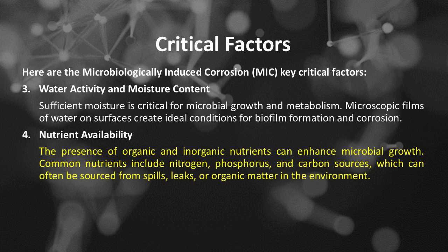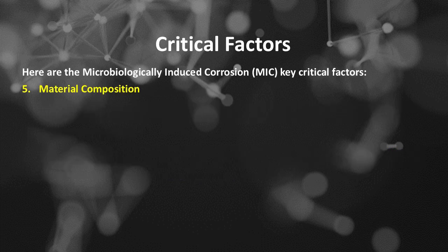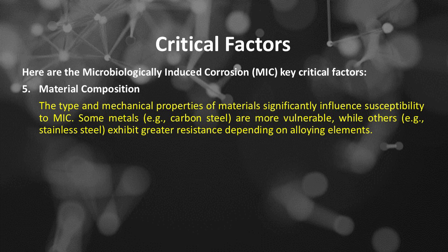Number 5 of the microbiologically induced corrosion, or MIC, key critical factors is material composition. The type and mechanical properties of materials significantly influence susceptibility to MIC. Some metals, such as carbon steel, are more vulnerable, while others, such as stainless steel, exhibit greater resistance depending on alloying elements.